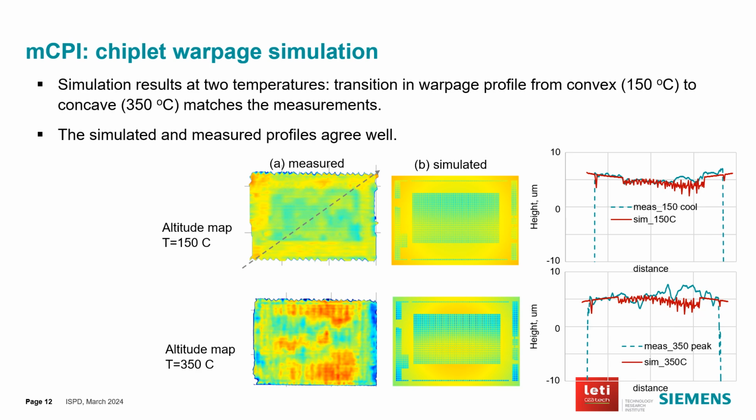After tool calibration, we obtained the simulation results on chiplet BOL surface at 2 different temperatures. In 1D profile along a diagonal direction, the simulated and measured results are compared. The central region shows micro bump microscale peaks corresponding to copper pillars that are exposed to air.